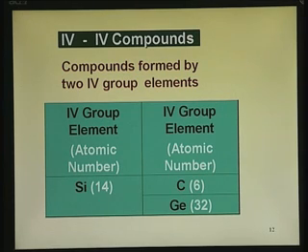And there is silicon germanium, an alloy of silicon and germanium. Both are semiconductors, please remember. When you mix them, both being indirect, you will get only an indirect band gap semiconductor. So, you cannot use it for optical applications. So, take this as 6.